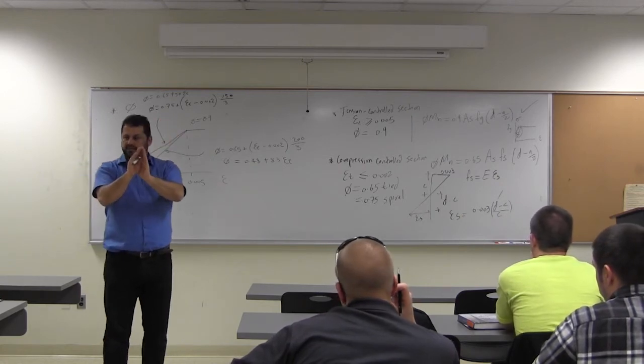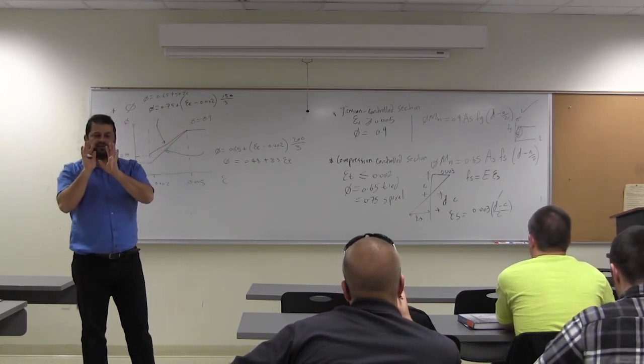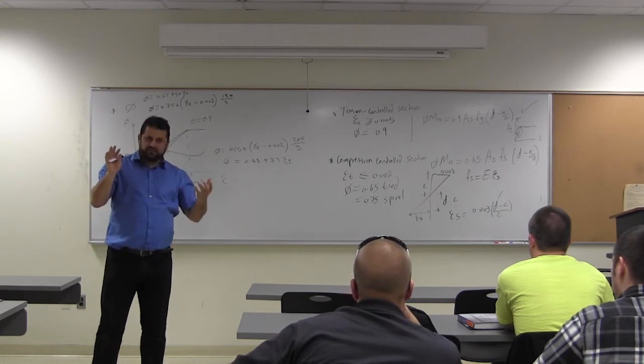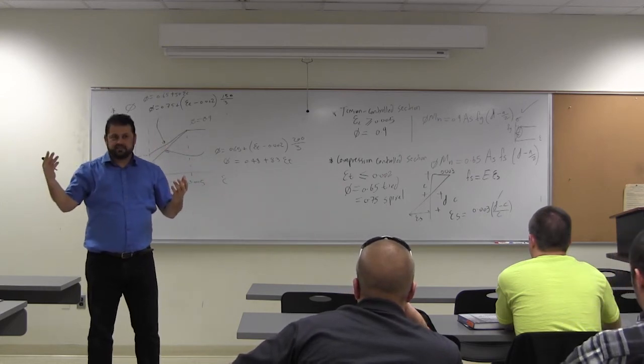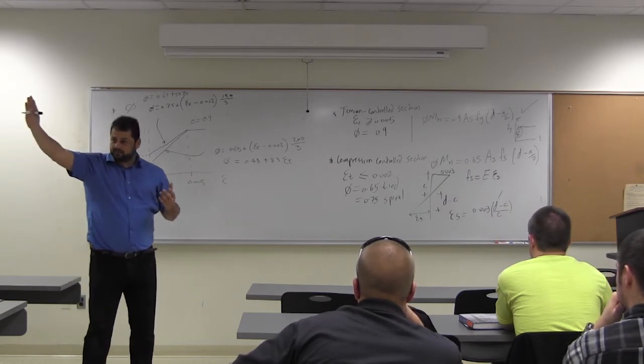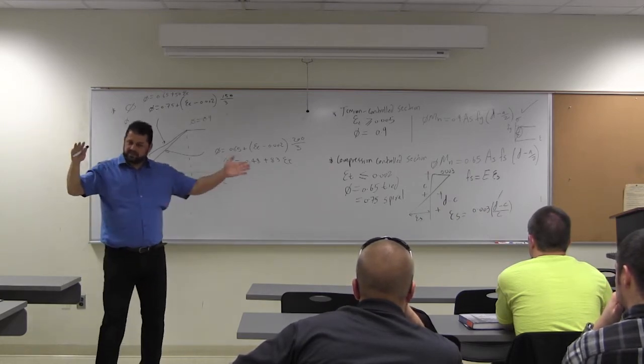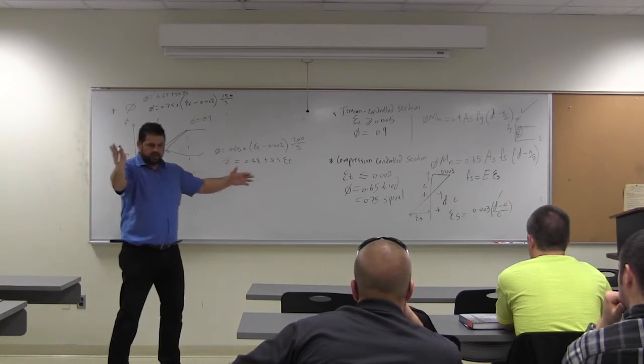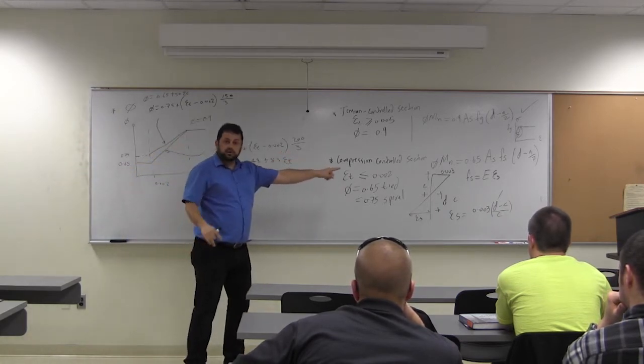And we said F prime C equal 4 KSI, it's 0.85. Less than that, 0.85. More than that, it decreases. Greater than 8 KSI, it stops at a certain number. Good? Between them, there's a function I told you about. You have it in your notes. So look what you have.